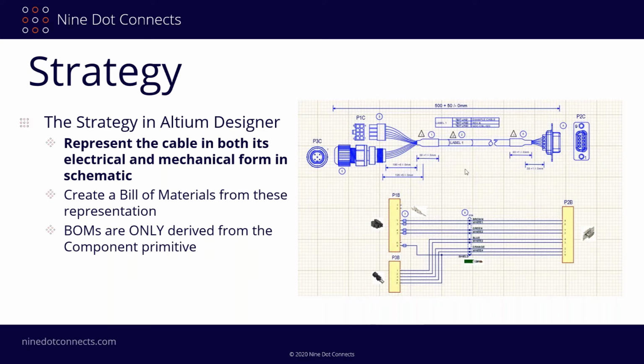I've only got 9 wires coming out of the P2B over here and spreading them out into 2 other connectors. But if this thing has 50, 60 lines, could even be more, then obviously trying to draw this isn't going to be very realistic here. And we would want to draw something that is useful to whoever's going to assemble it, but at the same time have something that can be easily read when they're actually trying to put things together pin to pin wise.